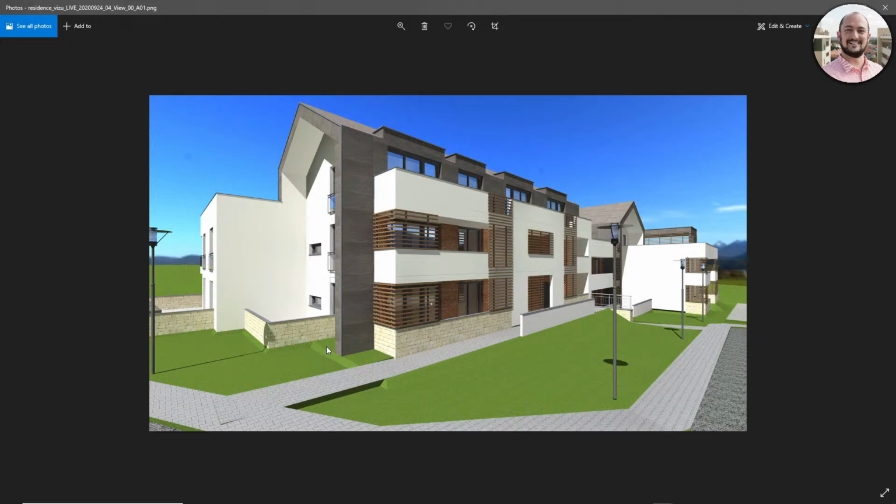But what happens if I increase the quality, if I increase this to detailed? If I increase the quality from quick to detailed, I can see a little bit more details, especially around corners, especially around small areas like this here. As you can see, I'm just switching between the two. There is just a little bit more depth for a little bit more of the rendering time. So this was quick and this was detailed. So this takes around 4 or 5 times longer, but it's a little bit more detailed.